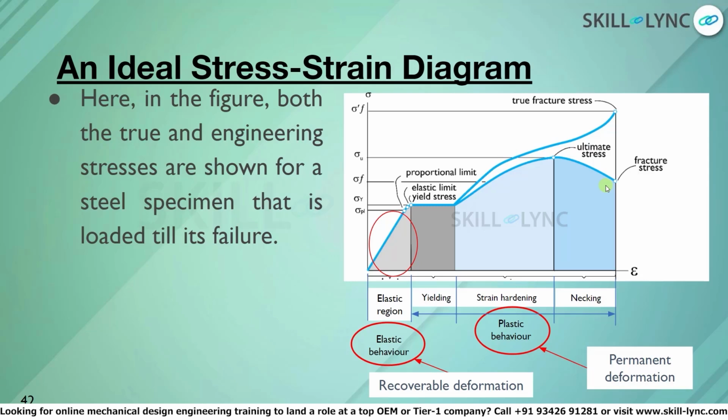Some important points to be noted here is that Young observed that the sigma epsilon slope was constant for any material independent of the sample geometry. This should be the same for any homogeneous material system. Also, there is very little difference between engineering stress and true stress. We can tell this from the diagram, as we can see that the difference in the graph only starts from the strain hardening region and deviates a little bit from there. Hence, there is very little difference, and this difference comes into play only when designing purpose is involved.